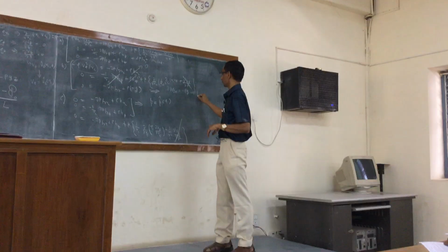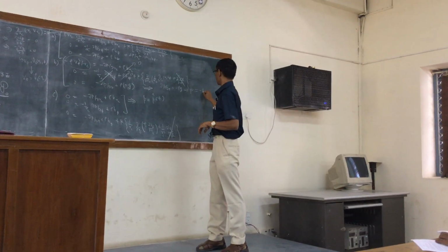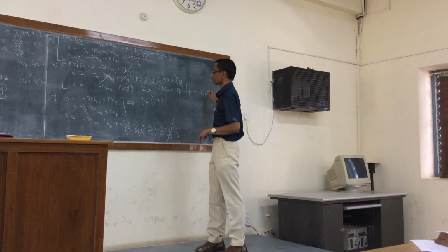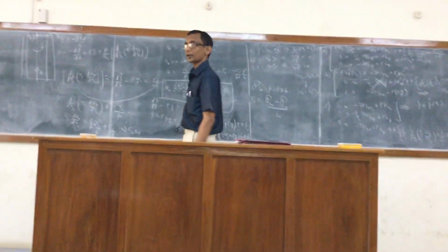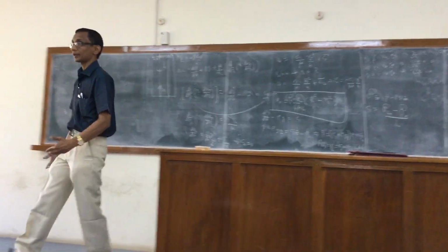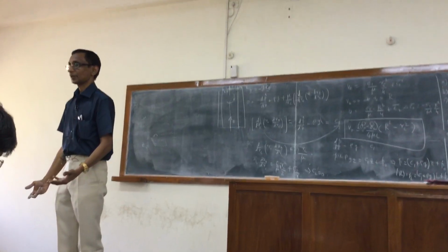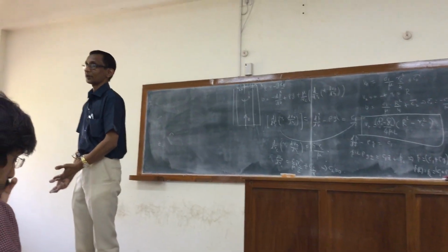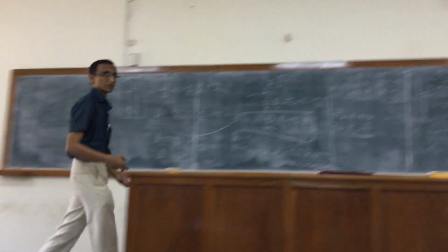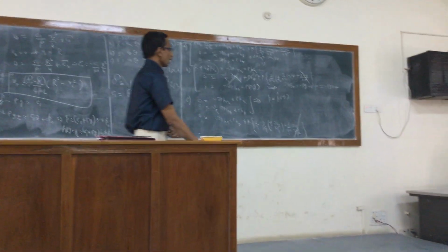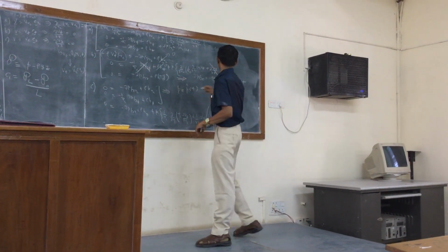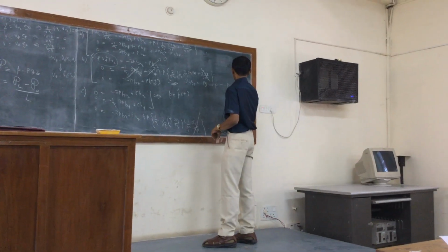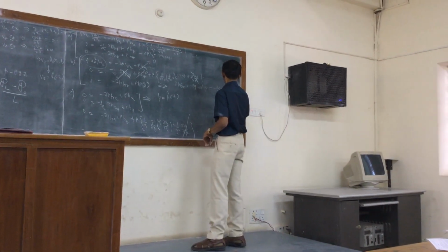I can integrate this. P is equal to minus rho g z plus, right, a function which in general can be a function of both Rc as well as phi. In general, just an integration, a partial differential equation in Z, right? However, by taking this assumption that dP by d phi equal to 0, I can make this some function of Rc alone.